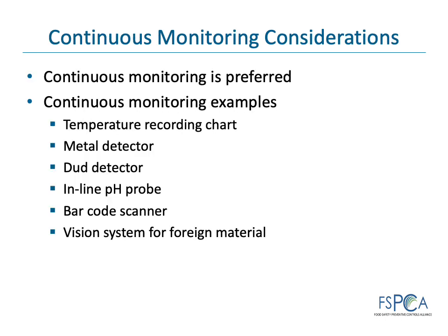When possible, continuous monitoring procedures should be used. Continuous monitoring is generally performed by an instrument that produces a continuous record. These records can be either affirmative records demonstrating temperature is controlled or exception records demonstrating loss of temperature control. See discussion below on exception records. The record needs to be checked by an individual periodically to ensure that the critical limit is being met. The length of time between checks directly affects the amount of rework or product loss that may occur when a critical limit deviation is found.